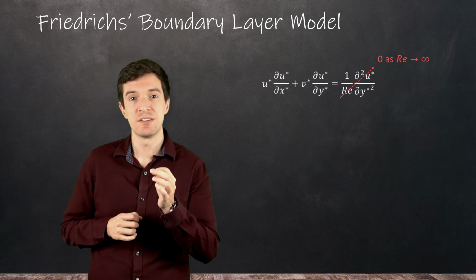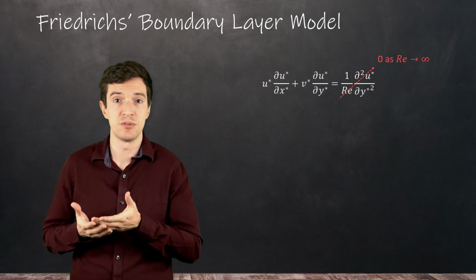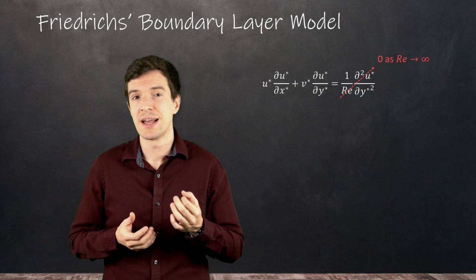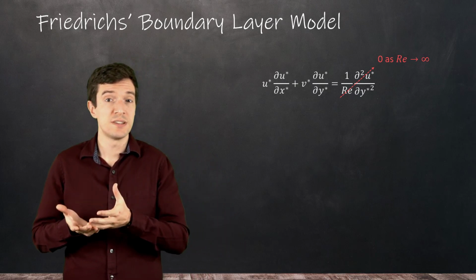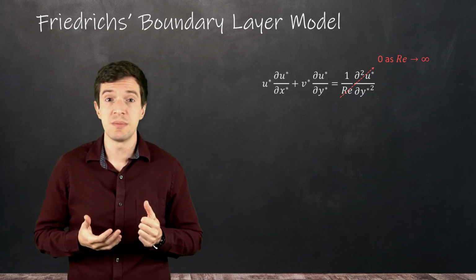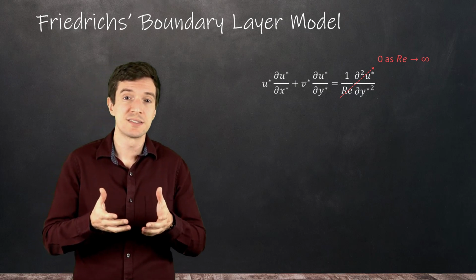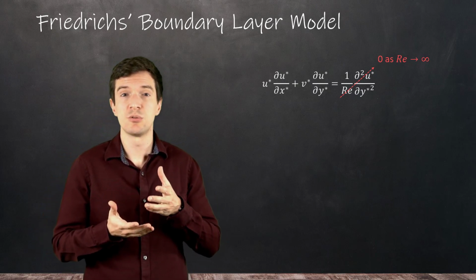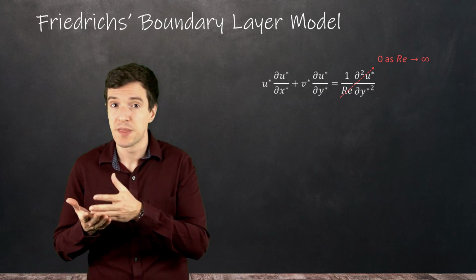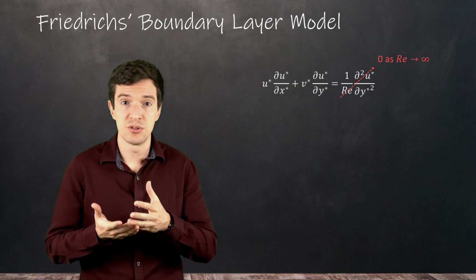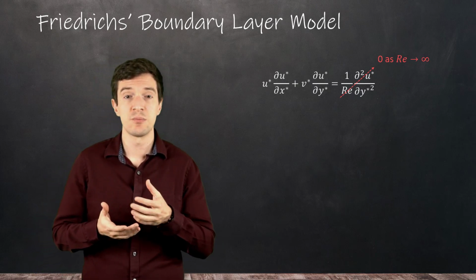However, even for large Reynolds number, we actually have no-slip condition at the wall. Hence, the boundary layer theory is not physical for extremely large Reynolds numbers. Friedrichs approached the problem to correct this limitation, and successively Van Dyke introduced an asymptotic methodology to provide a complete solution.